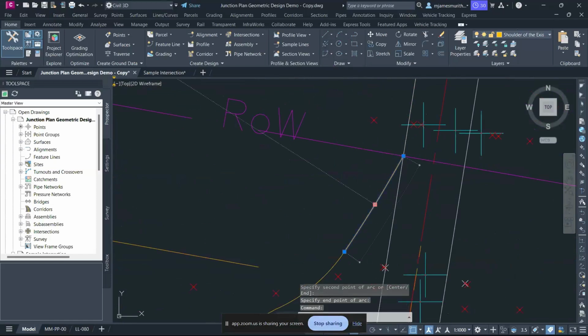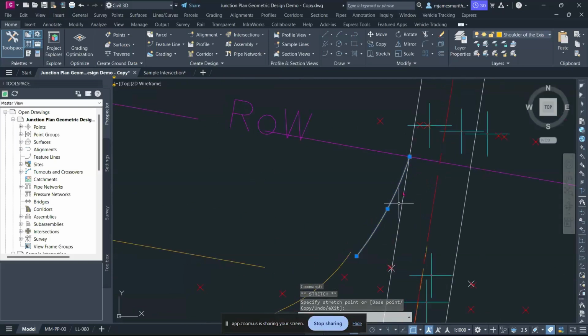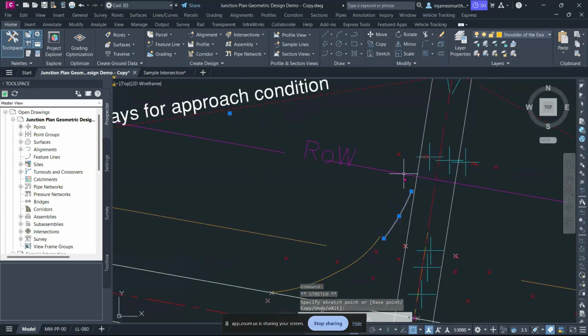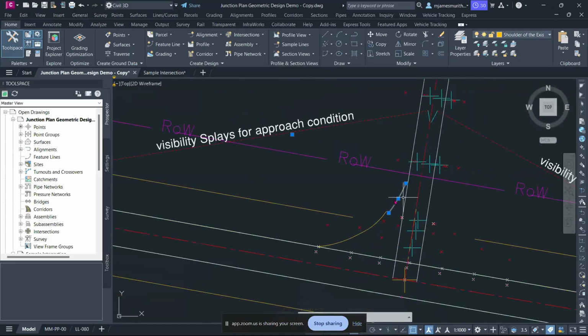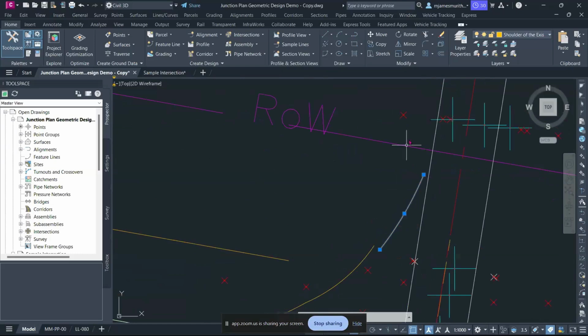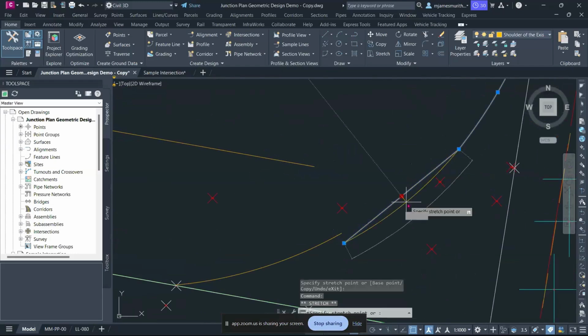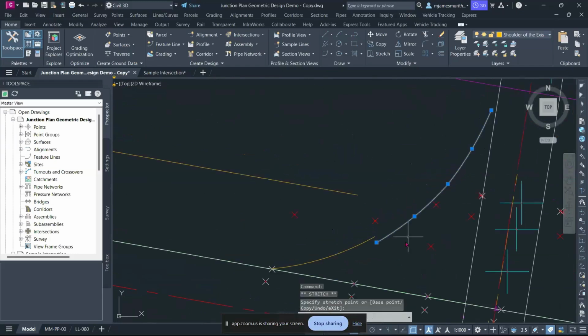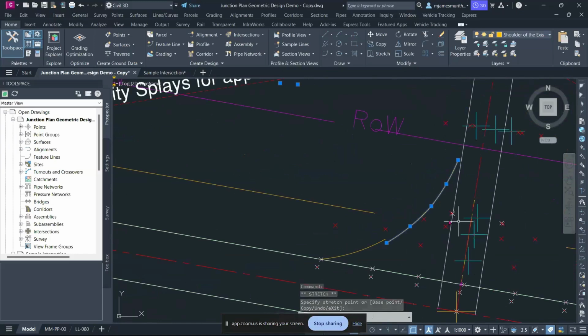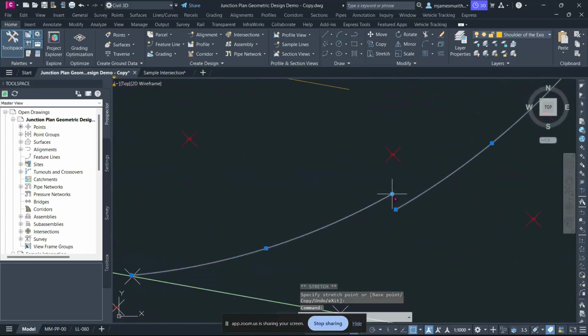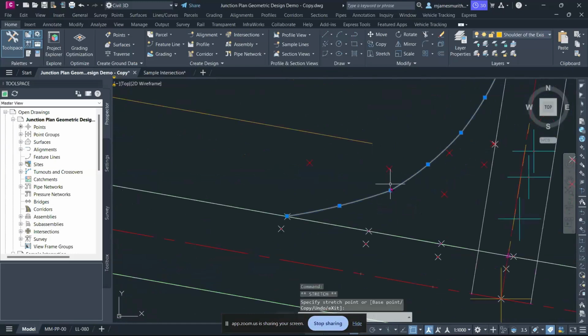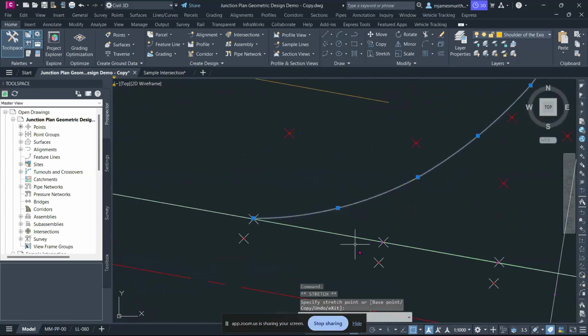So as I was earlier saying, you need to make sure by the time your road gets to the right of way, you've been able to taper it back to the normal width of the road, because these are parcels of land for other people. So ideally, you need now to start figuring out, how do I do these radii? How do I place them? And remember, already you've done your survey, you've gone to this site and you understand how the site looks like.